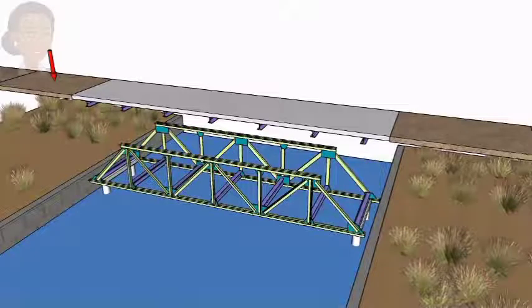When the truck enters the bridge, when the load is directly above the outermost beam, the entire load transfers to that beam. The load is then distributed to the 2 truss joints supporting the beam. When the truck moves forward, when it is somewhere between the first beam and the second beam, the load is distributed between the 2 beams in proportion to its distance from them. In turn, the beam loads are transferred to their respective end truss joints, like this. So, as the truck moves forward, this pattern of load transfer shifts forward from joint to joint until the vehicle leaves the bridge.